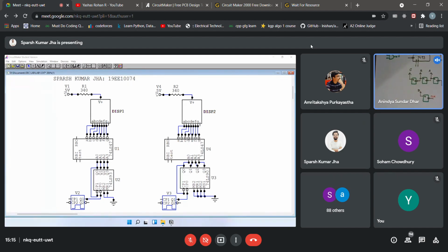Okay, can you come once again? What I think is this is being connected to D, then it is further being connected to the ABC. Right. So CP0 and Q0 are actually that lone flip-flop. You are giving the clock to the lone flip-flop, and its output you are giving to the next clock. The other 3, Q1, Q2, Q3, are basically whatever I have called ABC. So it is just the other way around: Q0 is D, that lone flip-flop. That connection is necessary, otherwise it will not work.